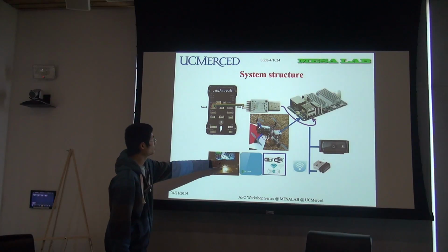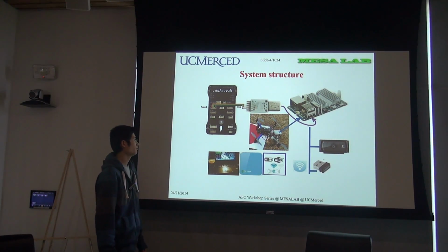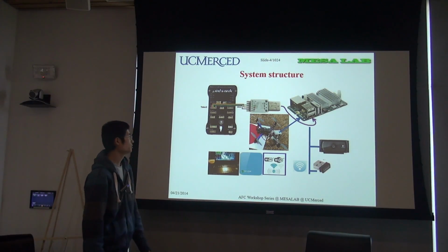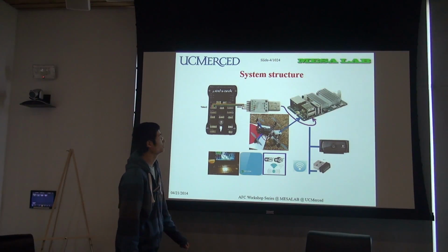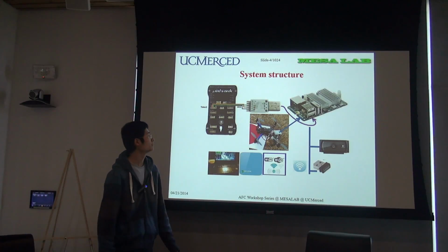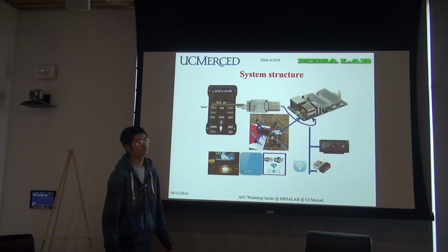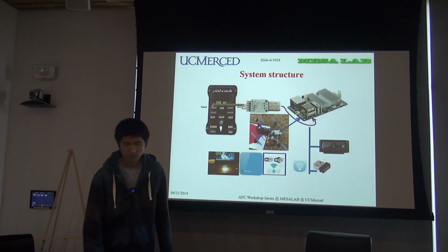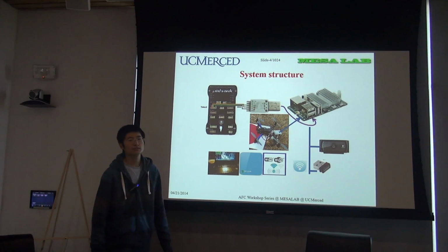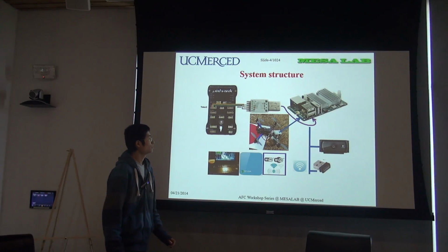We can use the ground station to see the real-time flight data from Mission Planner, and we can use Qt to log into the Android operating system to code and start the commands. We can also use the browser to look at the real-time image. We have developed a small app that can tune the red detection threshold in real time.